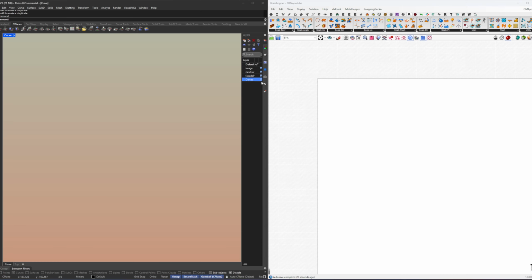Okay, let's go. The starting documents that we have are 3 different things. The first thing is that we need to draw 4 curves in Rhino, because they resemble the different elevations: north, east, south, and west. The second thing that we need to draw is the curves, because these curves will be the guides for the glazing system that's going to be wrapped around the building. As you can see, the glazing system is going over multiple facades at once.